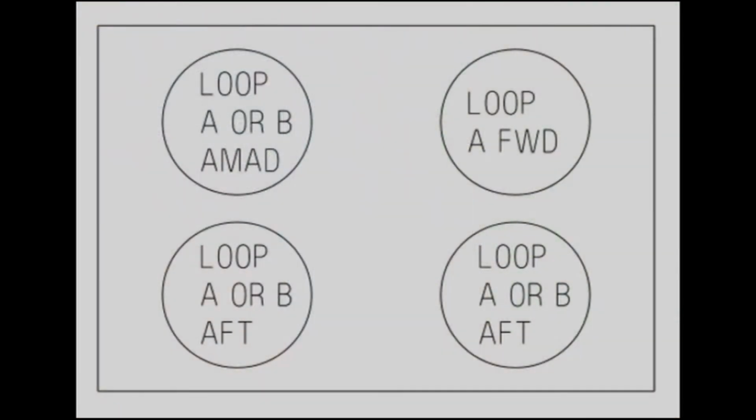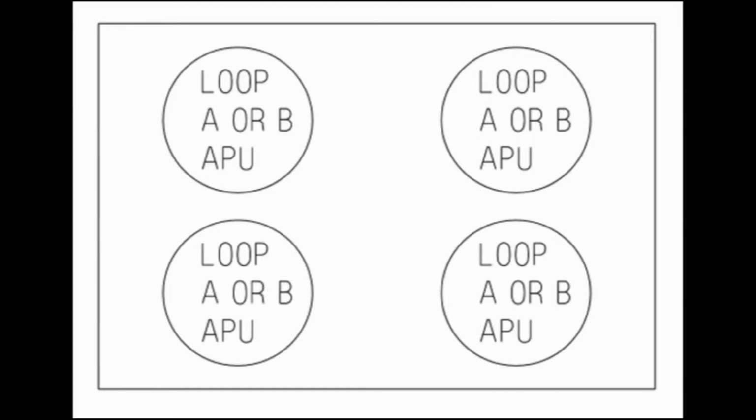In the event that any section of the left or right fire lights are not illuminated, refer to the IPB and MDART for your corresponding element that has failed. If APU fire light is not illuminated, refer to the IPB and MDART. In the event of a bleed air loop A or loop B failure, we will do a nose wheel well bleed air leak detection control unit reset.